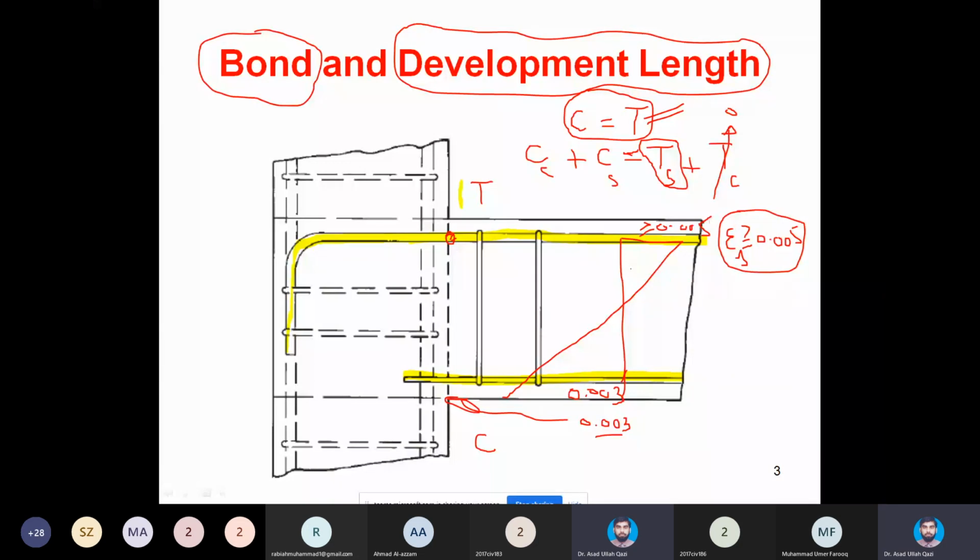Now the question arises: can I hold the steel without slip, and at this section can I get excessive yielding of this steel? Once it is subjected to tensile force, the bar will tend to be pulled out from this side and this side.